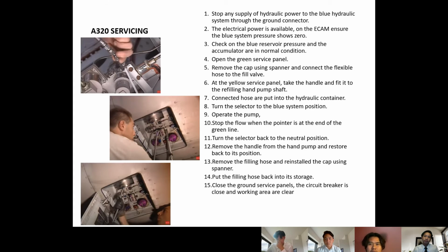Third, check that the blue reservoir pressure and the accumulator are in normal condition. Fourth, open the green service panel. Fifth, remove the cap using a spanner and connect the flexible hose to the fill valve. Sixth, at the yellow service panel, take the handle and fit it into the refilling hand pump shaft.